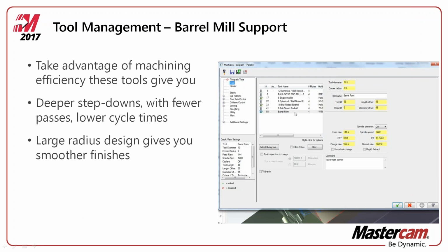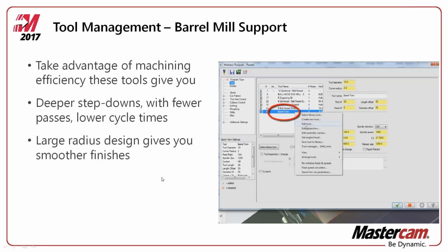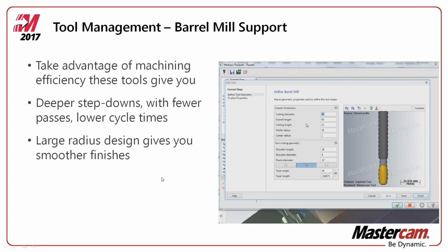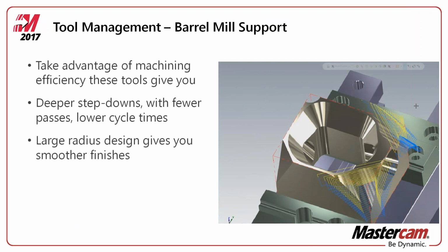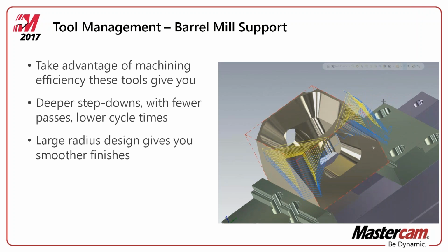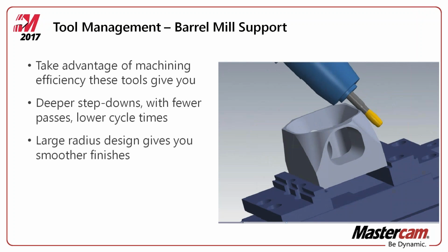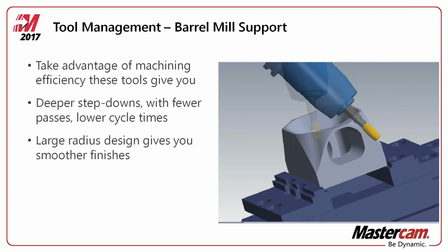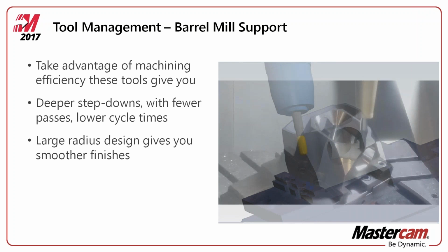Again, with the barrel mill support, there are some additions as far as using that barrel mill in a couple of different ways. If we right-click and say edit tool, of course we can import that model of the tool inside of here, and you can see if I were to use that toolpath, we can take a deeper step down with fewer passes and, of course, shorter cycle times.